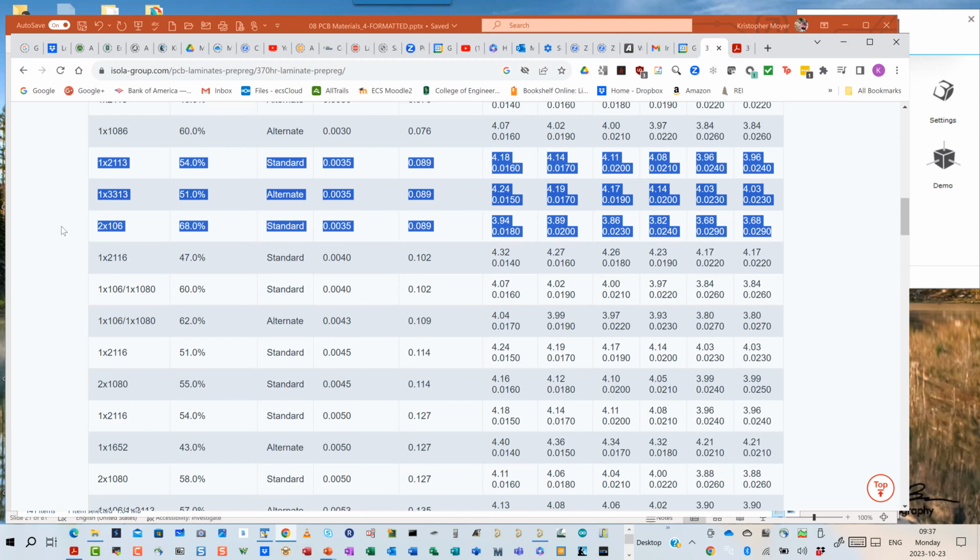So now you can see the difference that the laminate supplier went through to all achieve a core that was 3.5 mils thick, by applying different amounts of heat and different amounts of hydraulic pressure to their base materials before they applied their copper. So in this way, you can see why they have so many different constructions. And it says what sheets of prepreg material, meaning what sheets of glass with resin, they used to make these layers.